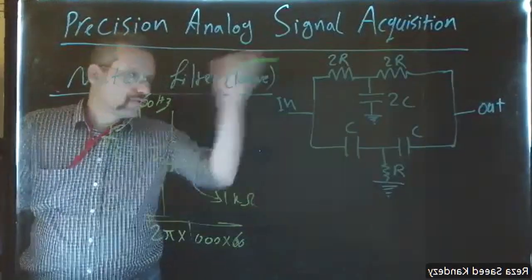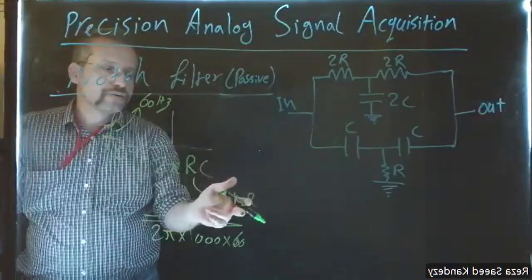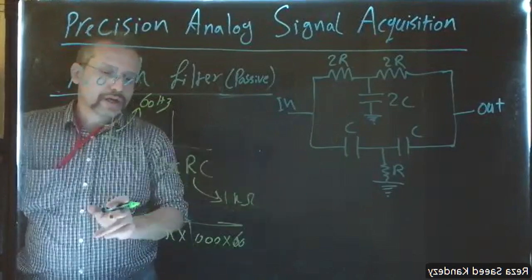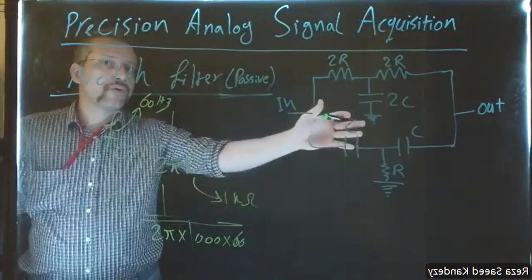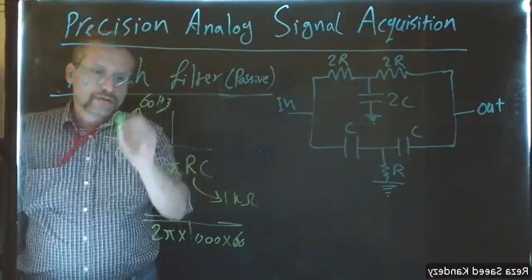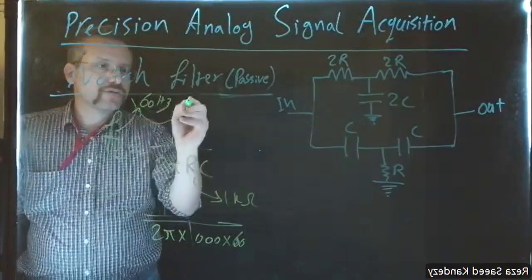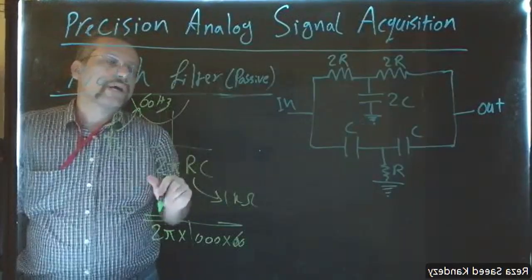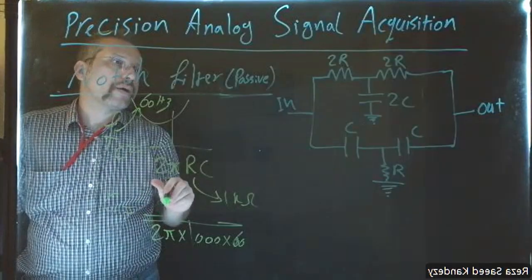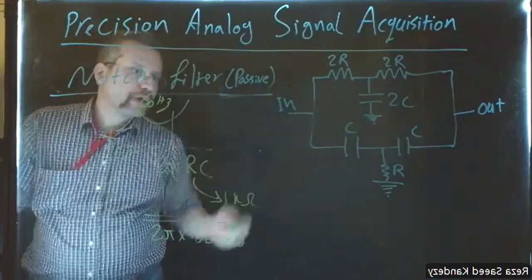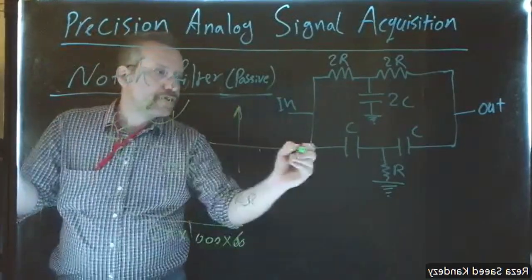Okay, you can choose other resistance values too. Basically, it would change the capacitor, but since we are working with a power line frequency, set the cutoff frequency for the passive circuit at 60 hertz, so you have a proper gain for your filter. Okay, and you are gonna see such a behavior.